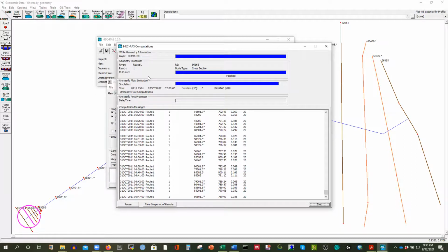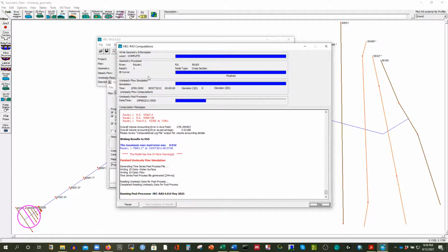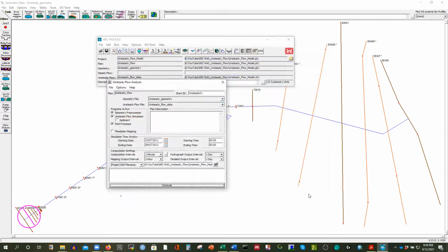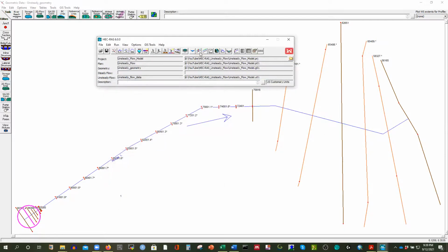If the model is stable with the appropriate boundary conditions, the flow data we have provided at the very upstream and the normal depth at the very downstream, it is going to match the downstream boundary condition, and it is going to create that 0.00023 from that upstream boundary condition. And in order to match that, this time it's multiplied 5 times. That's reasonable.